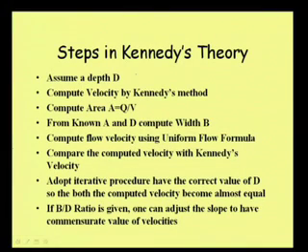I have explained it briefly, and now, step by step, what we can do is, first we need to assume the depth D. Then, using Kennedy's method, we compute the velocity V, that is the critical velocity. Then we compute the area from the continuity equation. Then, from the known area and the depth D, we compute the bed width B.